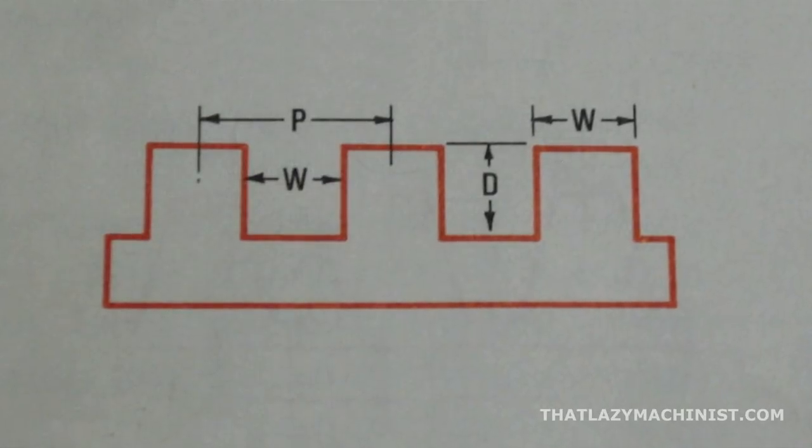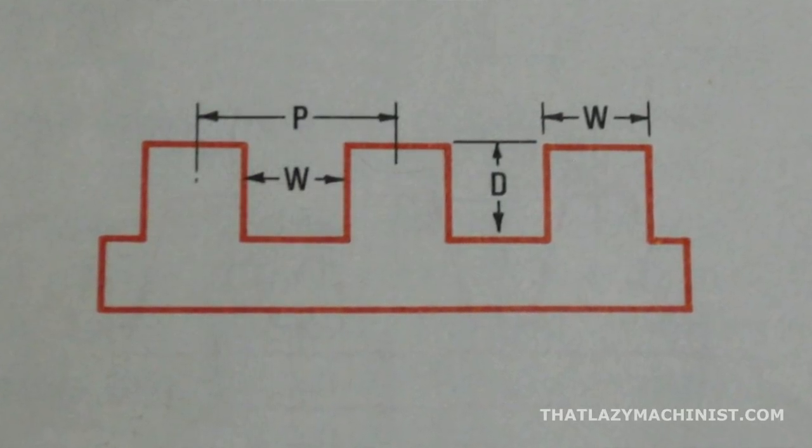So if the axial thrust is a problem, why not just use a square thread? They used to be used a lot, and they aren't used much anymore. Well, for two reasons. They are very difficult to produce, especially in a mass production way. And they are difficult to produce because the tool is prisoner of its own groove.